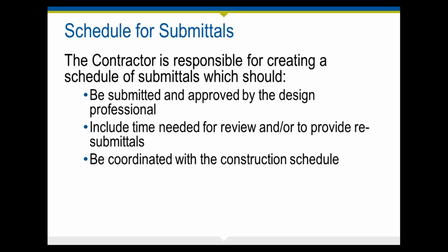Now, submittals are different. They are communication tools. This is how the contractor is telling you what they intend to do about the construction. How do they intend to build this thing? And your role is to review the submittals, the shop drawings, to see that they are indeed consistent with the design concept that is expressed in the drawings.